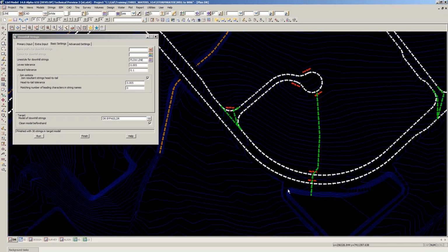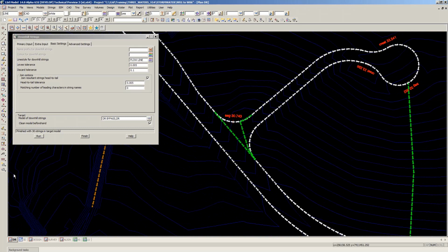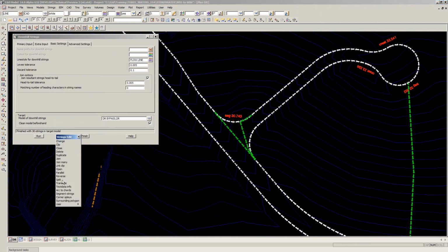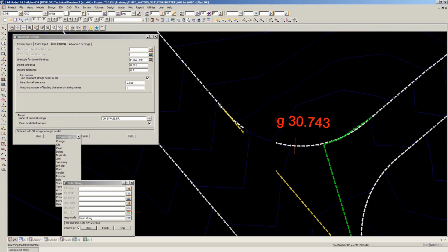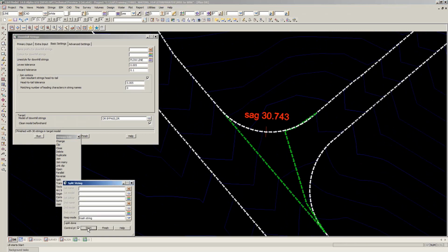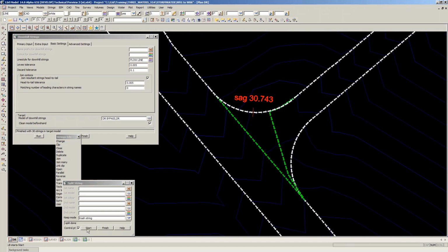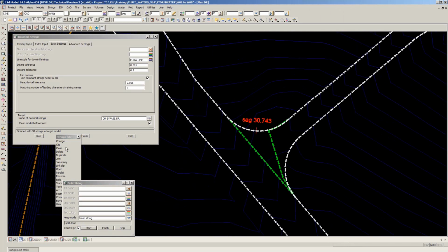But I'm not going to go through the whole model here and fix this, just to say that, hey, now you can do a little bit of intervention. And what I would do here typically is bring up my strings edit menu and go, I'll split, and I'll tick on the control point option there, and I want to split this grey string right at the start of that green string, like so, and I want to split this grey string right at the end of that green string, like so. And then I'm going to delete the leftover bits, which is that bit,